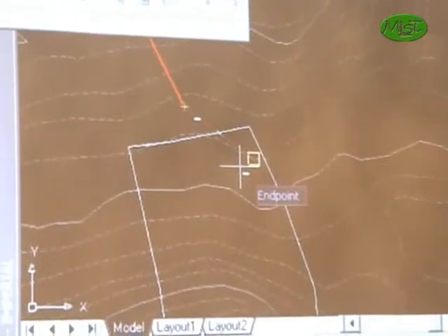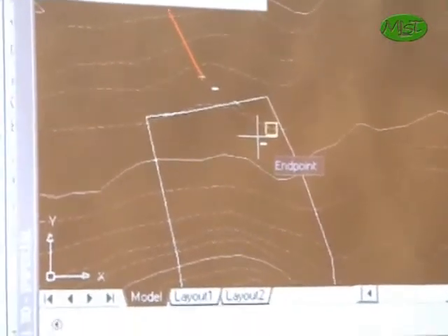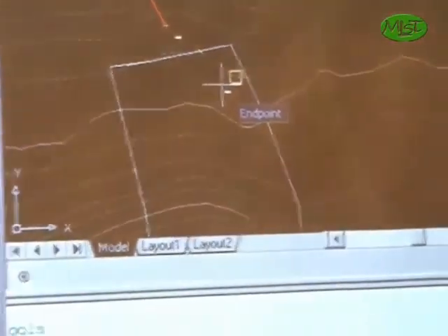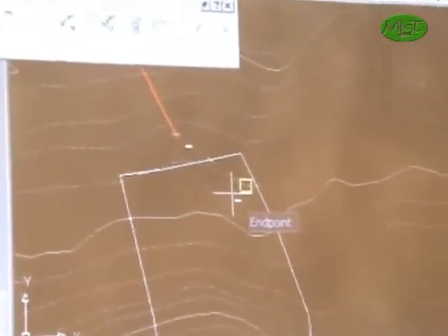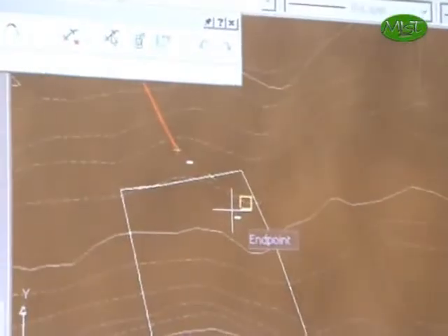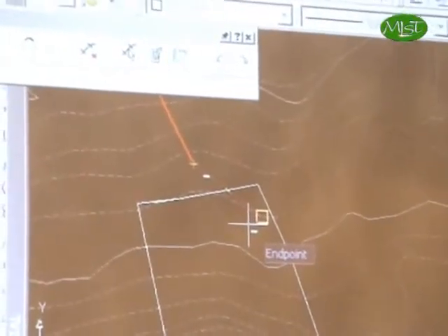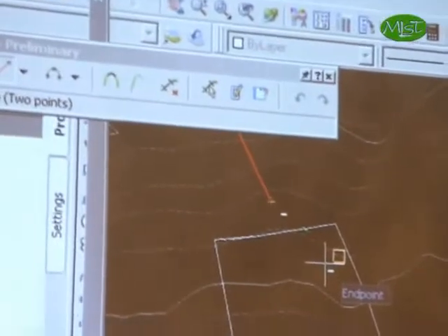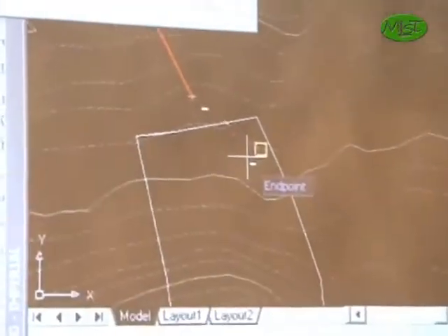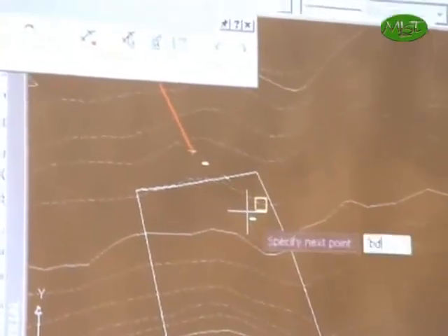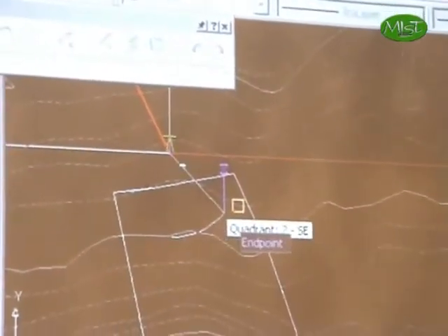Now, if you're using a previous application, sorry about that. Over here with Civil 3D, you can actually do some calculation as well. You can put in the number of quadrants you want, you can put in your distance, you can put in your bearing by going into this transparent bearing setting here.